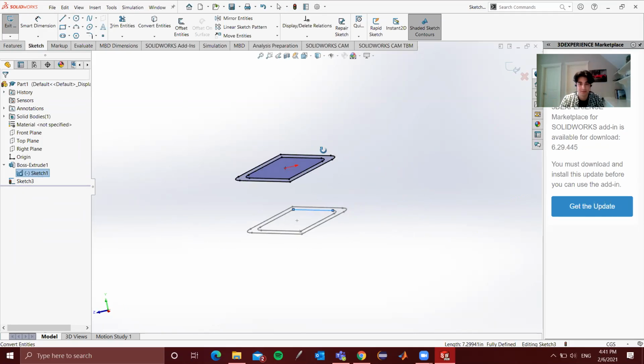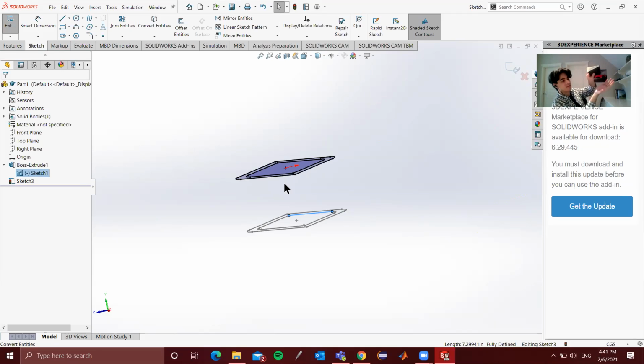Now, that's one way of doing it. The one thing I'll mention though is it is a projection. Similar to how, if you have some sort of object, like I have this notebook, it's essentially taking the shadow of it and projecting it onto your sketch plane. So the sketch plane would be my hand. Now, if you change the angle of it, you'll notice you're not actually getting the full length of what you want. So the sketch projection is based on a trigonometric ratio between your cosine and your hypotenuse, if that makes sense. So just be cognizant of that.